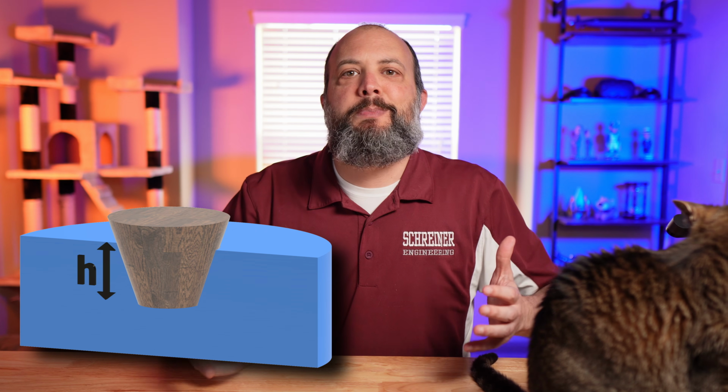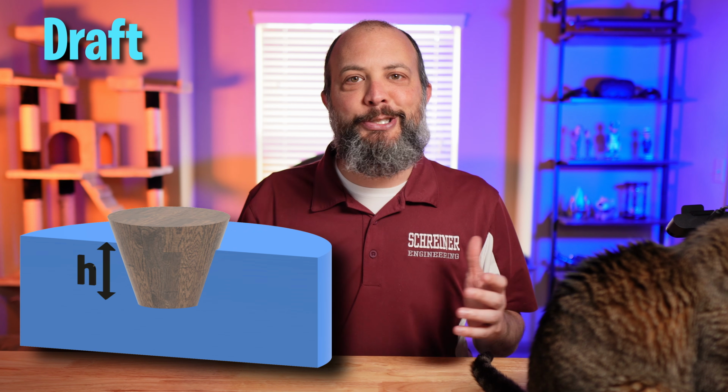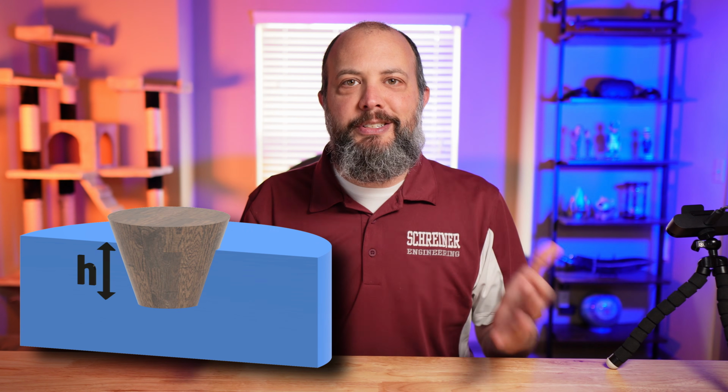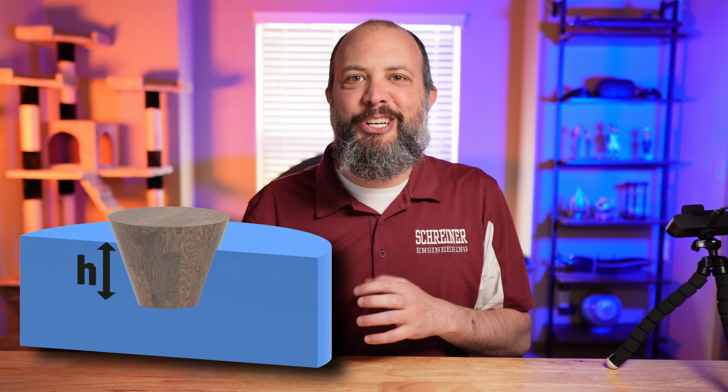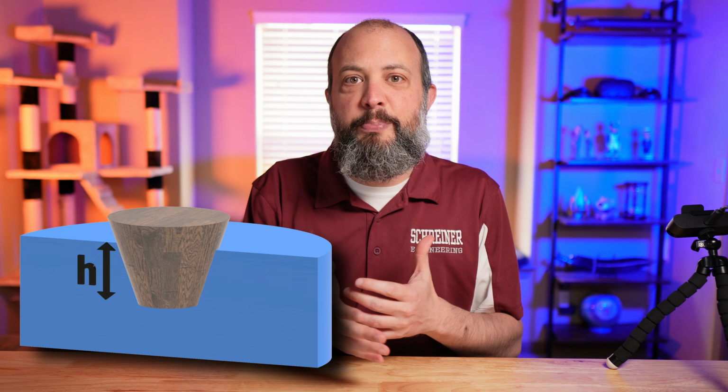This buoyancy problem is about calculating the draft of a floating body, also called the submerged depth or the fractional volume submerged. This example problem will use a truncated cone floating in water, but the same process could be used for any sort of ship or buoy.